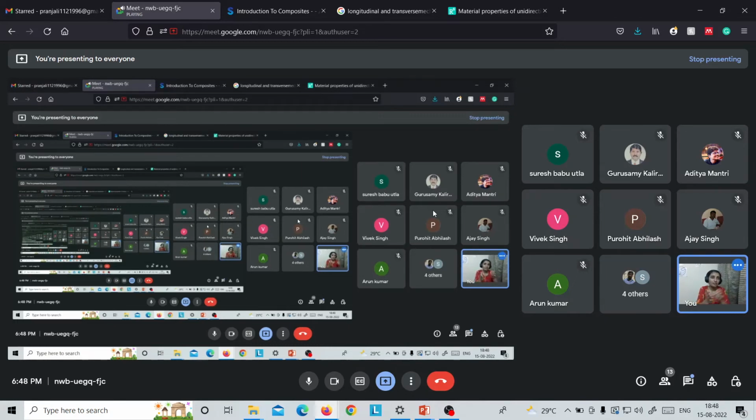Fine, because there is no melting temperature in thermosets. It's only the glass transition temperature at which a small change is seen, and then there is directly the degradation temperature. But in case of thermoplastics, we get two peaks. One is at the glass transition temperature where temporary bonds, that is hydrogen bonds and ionic bonds, are breaking, while in the second case, covalent bonds start breaking. So there would be property degradation at two stages, one at glass transition and one at melting. Am I clear?